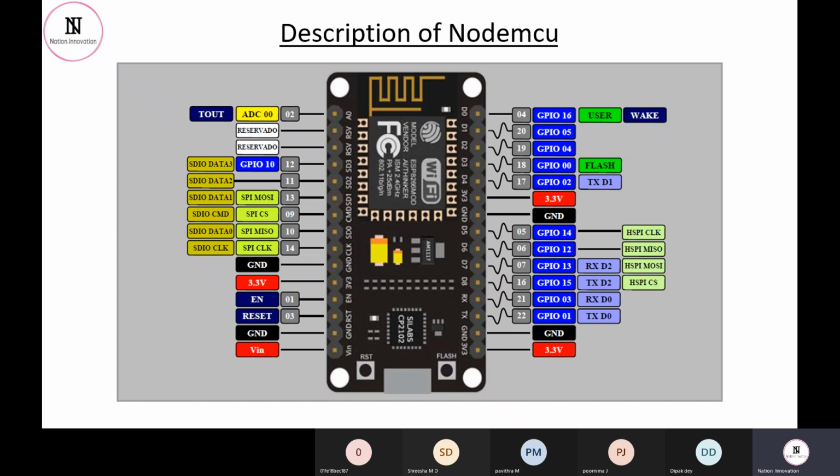Fine. If there is any doubt, please let me know. Before coming to the doubts, in this course we will be focusing on the Arduino as well as the NodeMCU. Why both? The reason is, if we use the direct Wi-Fi chip, the ESP8266, which is available for Arduino as well, this is a very sensitive chip.